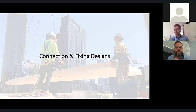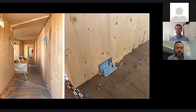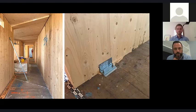So, connections and fixings. From a buildability perspective, I felt that 55 South Bank really captured a lot of efficiencies in this space. Of all the jobs I've seen around the world, it's probably got the least visual connection. What you see there is the corridor, as well as a zoom in on one of the connection details. In the corridor, all the screws are stitch screwed through the CLT into the floor below, and on the right-hand side, you can see the screw heads.